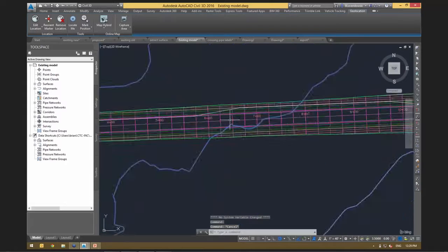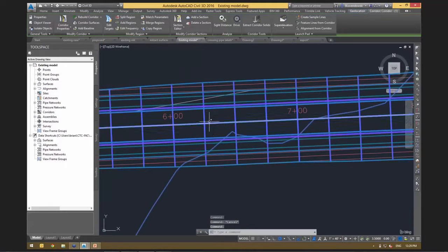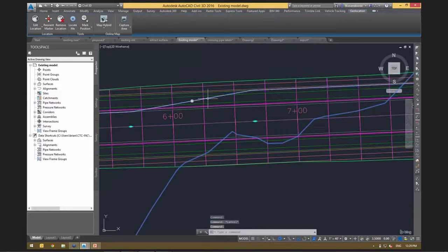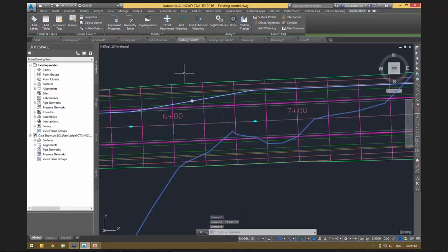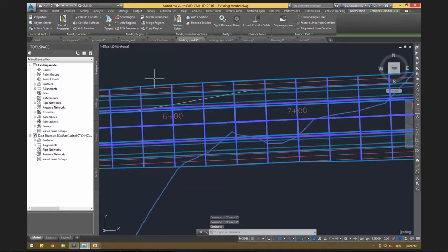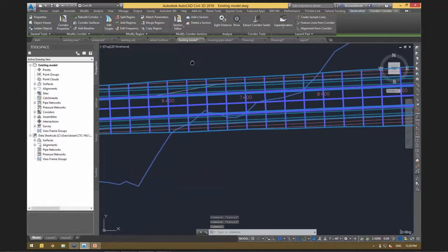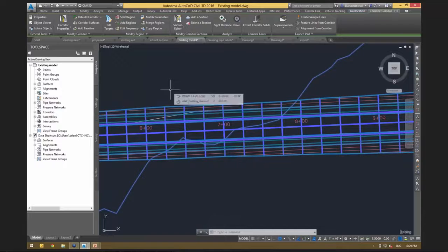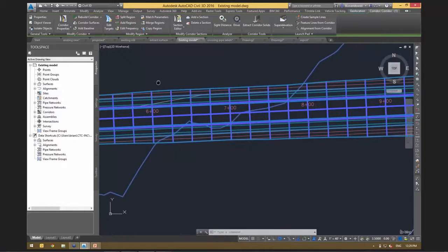So in here, I simply have a corridor right here, and I have an offset alignment defined. And this offset alignment is sitting on the C row dash left layer. This is just one alignment, but it could be many different alignments. I know some of our WisDOT consultants out there, corridor target objects need to always be alignments. There's many good reasons for that, but it makes target selection difficult sometimes. With this option, this is now considerably easier.